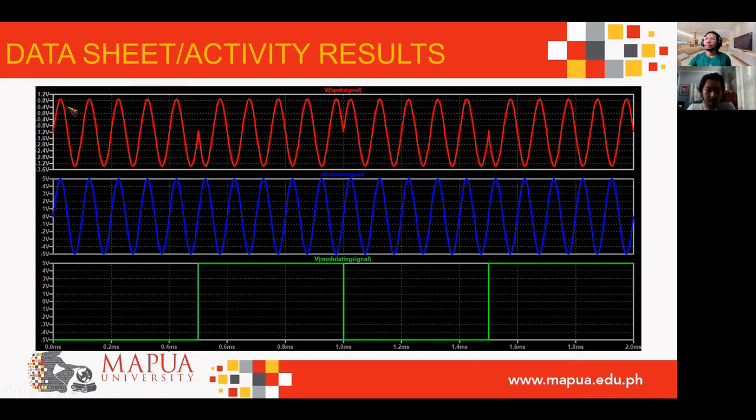As we can see, when the modulating signal transitions from low input to high input, the phase of the signal reverses. From 0 to 1, the phase reverses as seen on the graph of the BPSK signal. Then again, when transitioning from high input to low input, the phase reverses. Then when it transitions again from low input to high input, the phase of the BPSK signal reverses again.